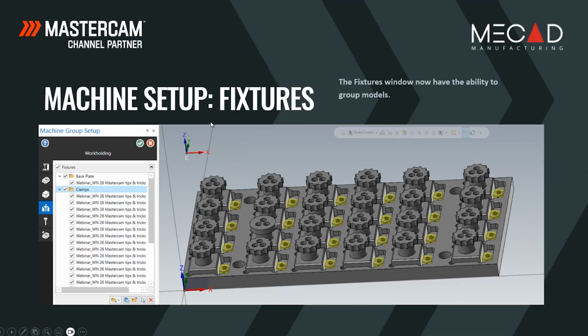In your machine setup under the fixtures, there are now groups added. For example, you can see all our clamps are currently selected because our clamps group itself is selected. What makes it nice is, let's say you have an issue with your clamps, like your tool is crashing or something, you can either enable or disable it there. If you disable a single group, it'll disable all of them at once because they are under that group. If you want to enable it again, you just click that tick and everything in that group will be enabled.